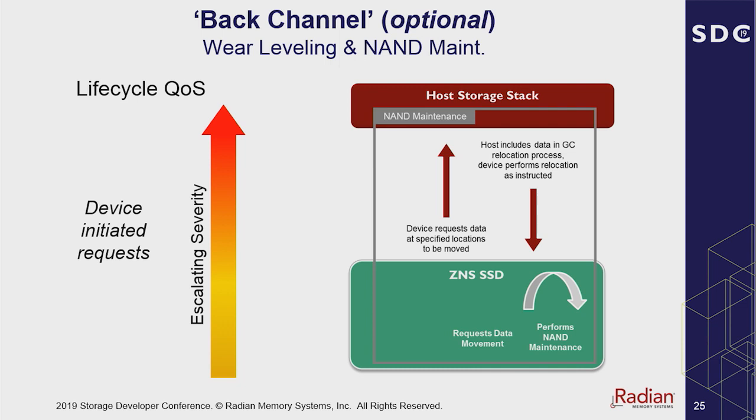While this is the simplest approach for a host, and the events are fairly rare in the first years of use, just as with any SSD, they will start to increase over the life of the drive. So to maintain consistent quality of service over the life of the drive, the host should, as a matter of policy, plan to service the requests. Otherwise, the maintenance and relocation spikes will create uneven latency profiles. But in either case, the data reliability will be maintained, as the device will ultimately not allow the request to go unserviced, which is what enables SSD vendor-supported warranties.